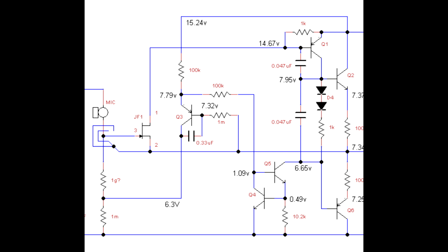All right, the final trick to the circuit is that the output is tied directly to the source of the JFET. So instead of being connected to ground or referenced to ground in some sort of way, the source is referenced to the actual output itself.